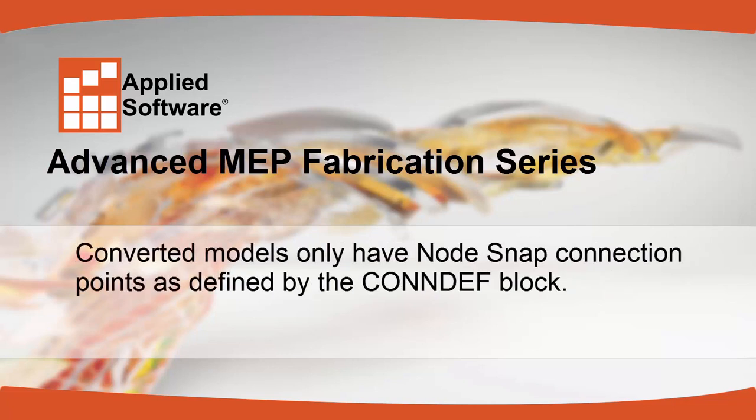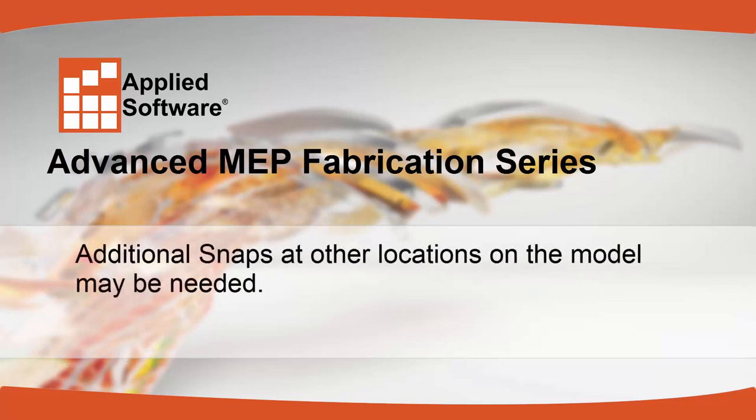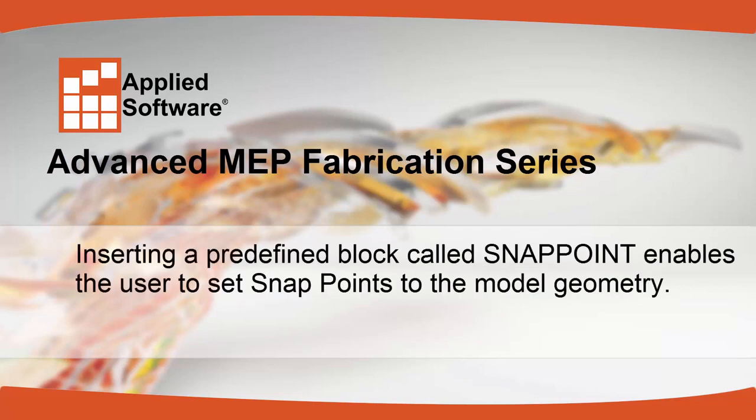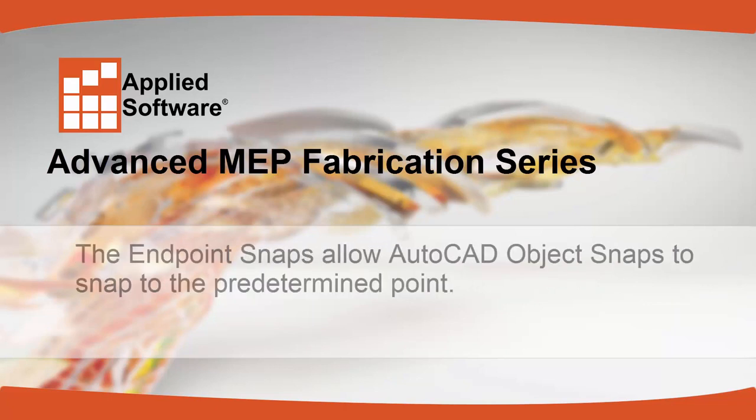Converted models only have node snap connection points as defined by the ConDef block. Additional snaps at other locations on the model may be needed. Inserting a predefined block called Snap Point enables the user to set snap points to the model geometry. All snap point blocks will be converted to endpoint snaps. The endpoint snaps allow AutoCAD object snaps to snap to the predetermined point.